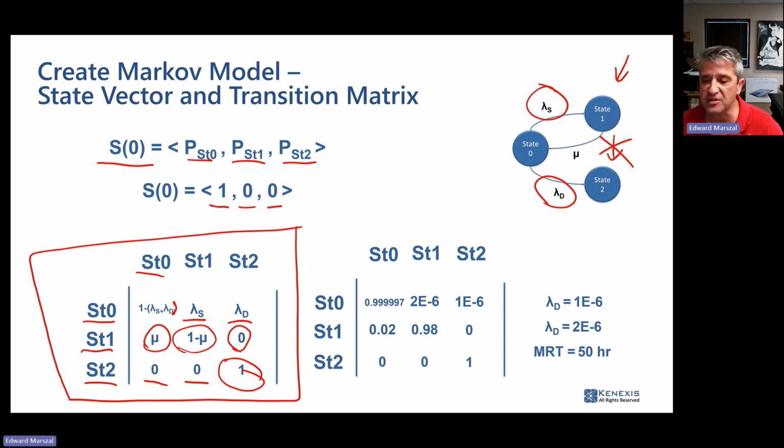When you use the analytical solution equations that are present in the ISA technical report on SIL verification calculations, that's what you got. You've got an analytical solution. But when you use a Markov model, you're actually doing a numeric approximation of what the analytical solution equations will give you.